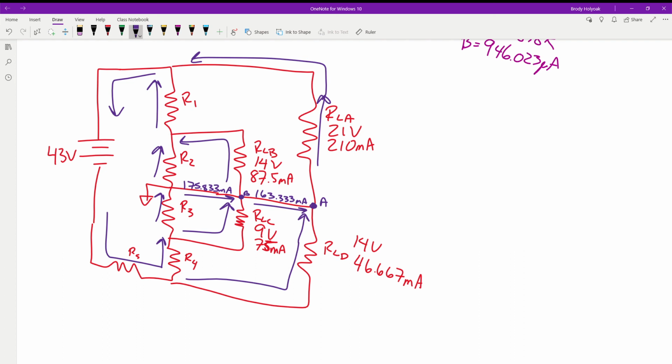Okay? Now we're going to look at these values. So looking at this, which one would we expect to see our bleeder current? R3 or R2? R2. Because if we look at this guy, we have current coming in, current leaving. More likely than not, this is going to be our bleeder current. Bleeder never touches the load. I just was going to show that we could figure it out without looking at that.